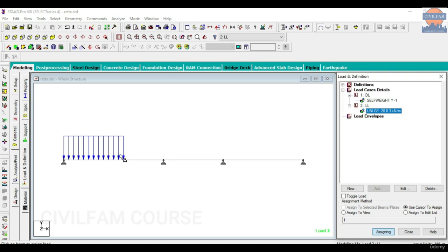Now when can this kind of condition come to you? See, this generally happens when you have what you call a balcony. Okay, you have got your wall to a certain extent and then the balcony railings will come. So if you want to scale back on the amount of loads you're adding to your system to get accurate results, that time you can use this method. All right, so until where the wall is coming, you apply the wall load like this, and then for the balcony you can let it be because 0.75 kilonewton per meter we add anyway on the balcony beam on top of it. Okay, so you can do this in that condition.